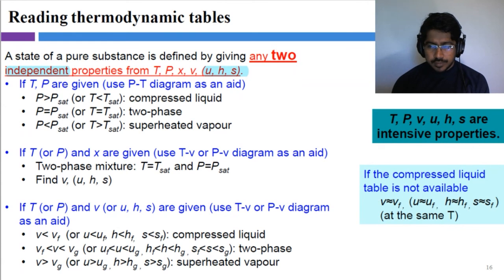There's another answer saying yes. I believe Deza is right, because we cannot determine a state inside the dome using temperature and pressure only, because these two are not independent parameters. Inside the dome, for a given temperature, we know the pressure.